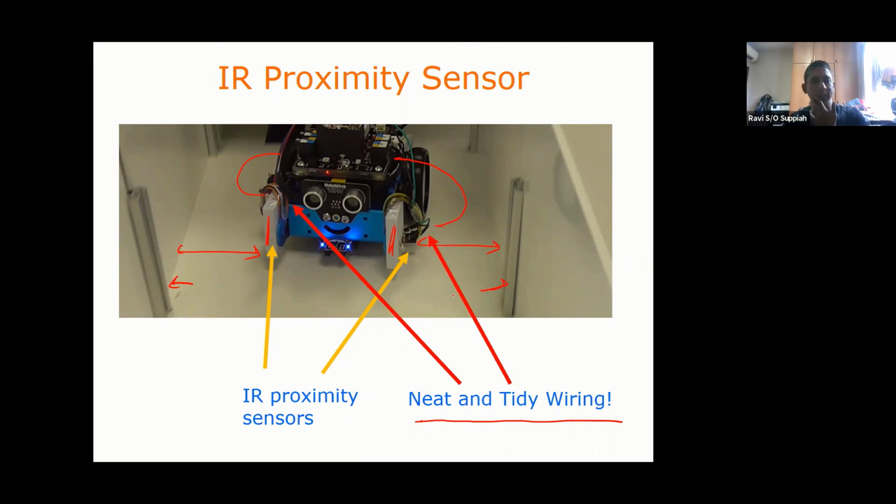So it's important that you do not have any wires or anything loosely hanging out of the robot in any way. Everything should be very tightly wrapped around the robot. Those are some of the things you need to do. If you see down here, they have used scotch tape. You can use scotch tape, you can use blue tack, or whatever you need to make sure that everything is secure and tight on your M board.